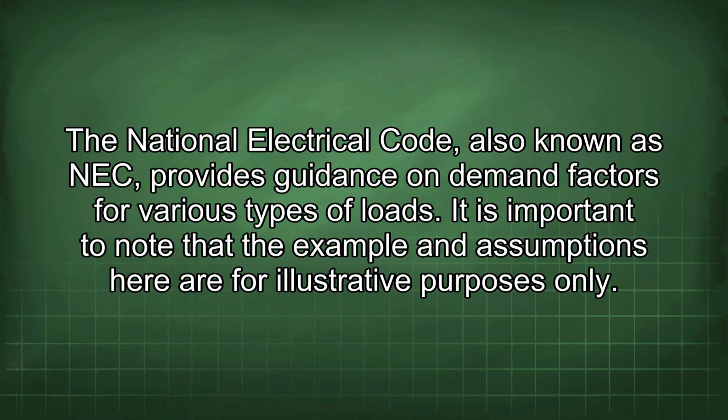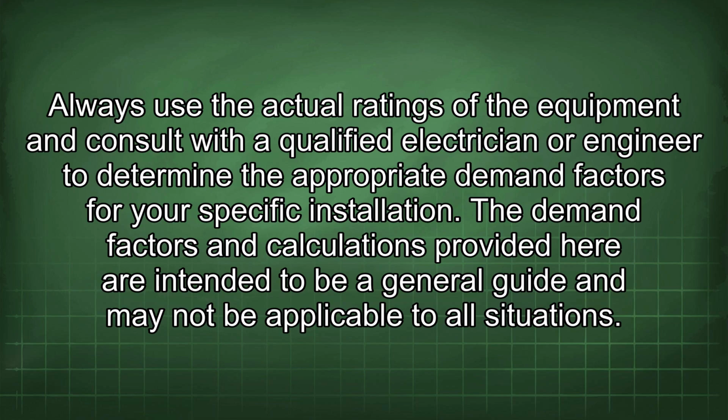It's important to consult the local electrical codes and regulations to ensure that the demand factors used are compliant. The National Electrical Code, also known as NEC, provides guidance on demand factors for various types of loads. It is important to note that the example and assumptions here are for illustrative purposes only. Always use the actual ratings of the equipment and consult with a qualified electrician or engineer to determine the appropriate demand factors for your specific installation.